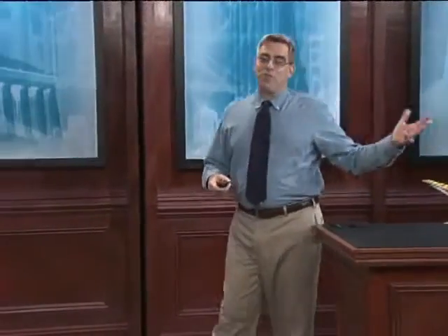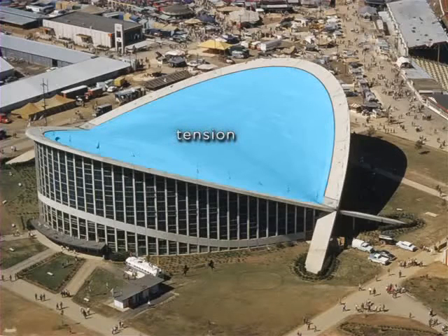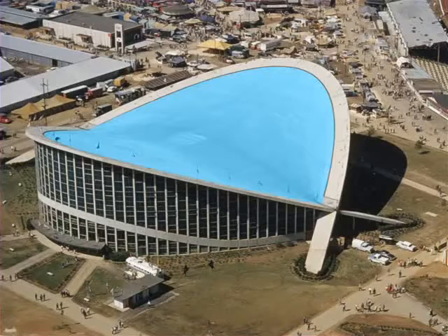In fact, the structural system of the Dorton Arena is actually very similar to a common director's chair, which uses the tension in the fabric seat to hold up the chair, just as the Dorton Arena's cable roof structure helps hold up the arches. Now, at this point, I should explain something that you've probably already noticed in the model. The cable roof of the Dorton Arena carries load entirely in tension. It's a tension structure. But the structural system as a whole actually includes some critically important compression elements as well, those two massive concrete arches.